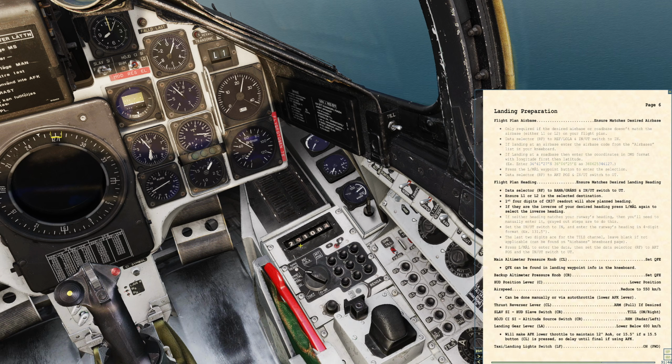So it's now showing us 2910, which in fact is correct for that runway, and it's still confirming to us runway 04. So we've done that. We've pressed the button, so we've selected the inverse heading, and we can now put the system back into actual position, and we can flip back and forth. You see that the L is flashing. It's just confirming to us that we've actually modified it from the default setting. So that's nothing to worry about.